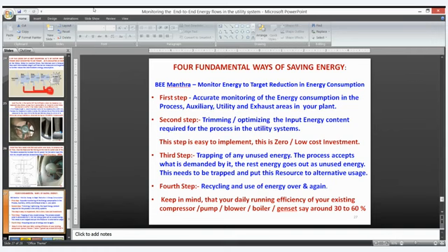See, for some of the waste collection systems, the OEM or the process man said we have to operate at 1000 pascals. But now many in the textile industry segment are operating at 500 pascals and they are doing an excellent job. So the OEM always talks about the safety of the machine or safety of the process, but energy saving is also a priority. Let us try to optimize the energy influencing parameters. Optimize the pascals in all your blowers. You will see an immediate 3 to 4 months payback, an immediate result, and your energy bills will reduce right from day one.